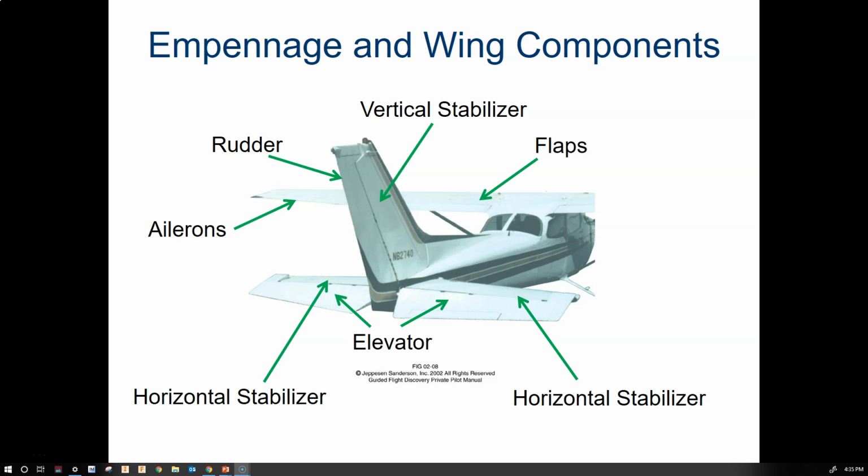The rudder, there's just one of them, is on the back of the vertical stabilizer, and it controls yaw. It acts very similar to how the elevator and ailerons act in that it moves, in this case, left and right. But the horizontal stabilizer, the vertical stabilizer, and the wings are pretty much the same, which means that they have some camber to them and they allow for a change in force, whether that be a lifting force or a force that allows you to have a lift in a horizontal direction that induces yaw like the vertical stabilizer does.